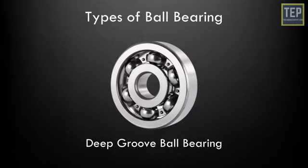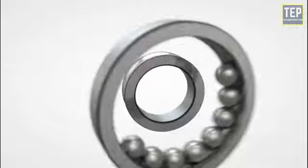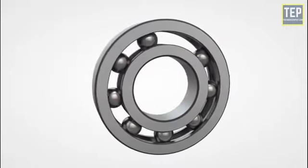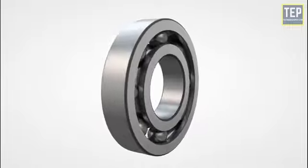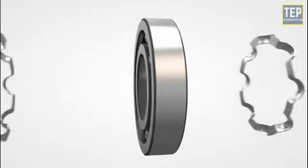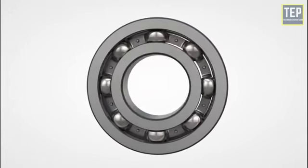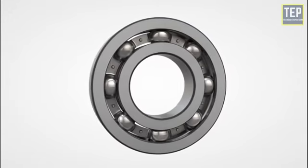This is the most widely used ball bearing. Trapped between the two races is a ring of balls that transmit the load and allow rotational motion between the two races. The balls are held in place by a retainer. They have very low rolling friction and are optimized for low noise and low vibration.